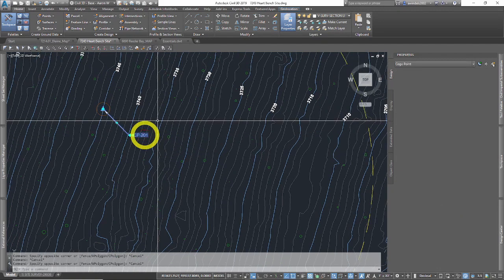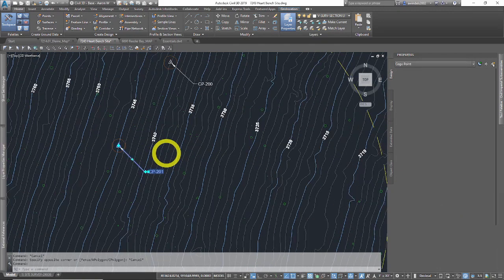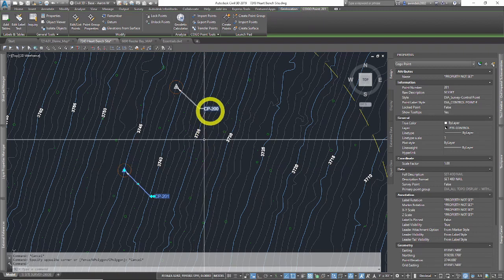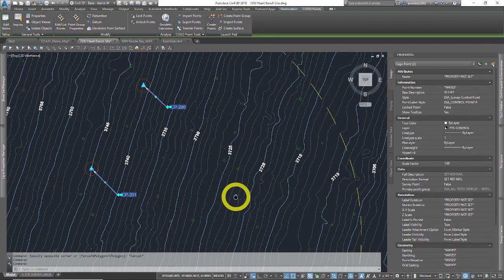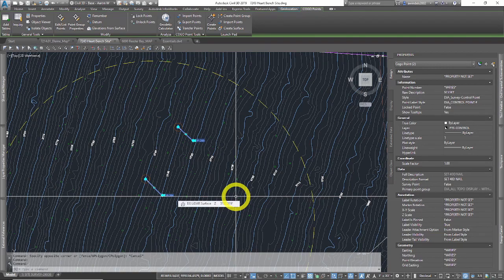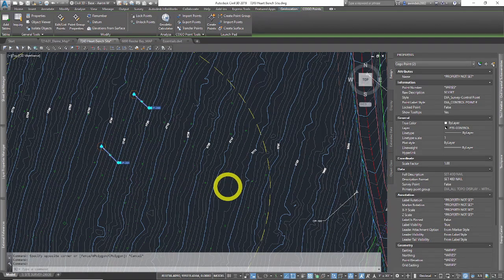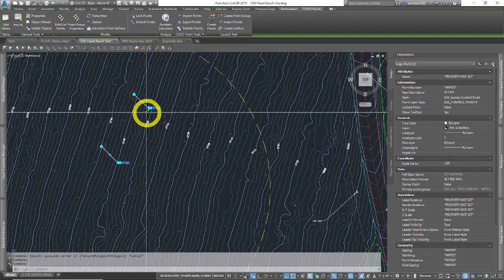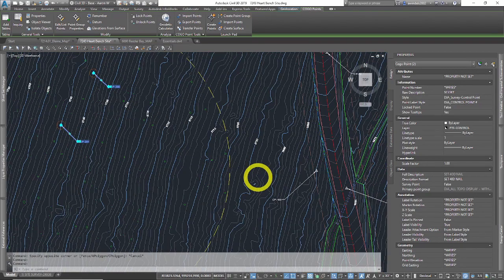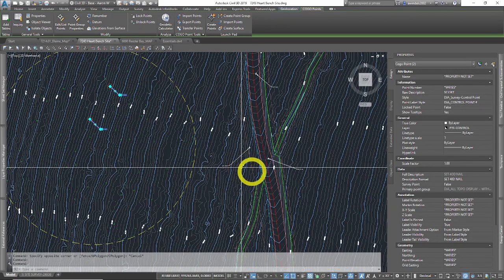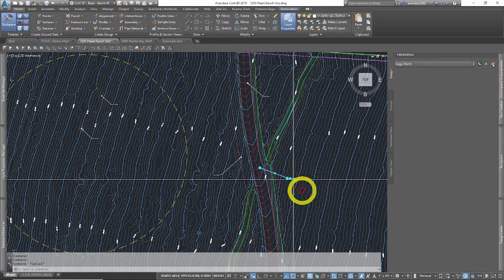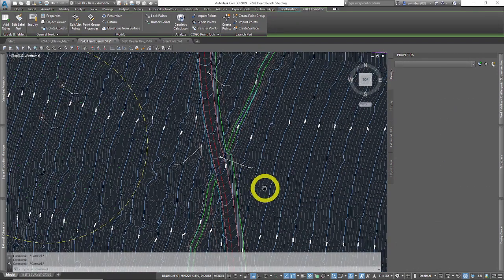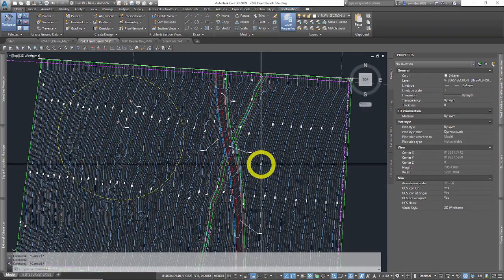But control points are a critical piece of any survey, in that they are what controls how all the other points' accuracy is reflected from. They are where you survey from, correct your data from, all the data runs through, whether it be a total station or GPS RTK survey setup. They are very critical, and where they're placed, how they can be accessed in the future, if they are very permanent entities to be found and used again, all comes into play in the accuracy and the type of map we want.